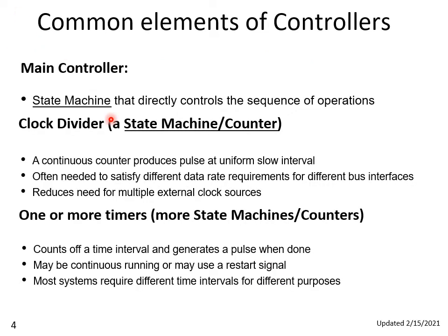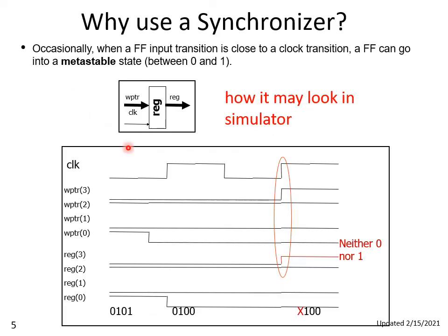And this is just a summary of what we discussed moments ago. I want to spend a little more time thinking about synchronizers and why we need them. So you know how they're designed. They're very simple. Two flip-flops chained together. You already know how to write the Verilog code for it, but I would like to make sure you have a little better understanding of the behavior of them.